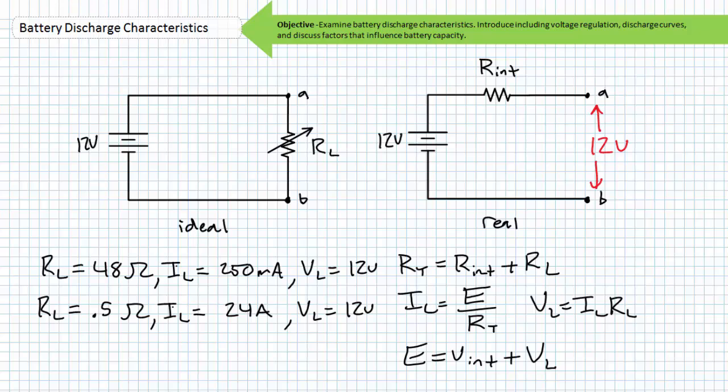of self-discharge over time. When an electrical load is connected to the battery, the internal resistance and the electrical load are placed in series with one another. The 12-volt source sees not just the resistance of the electrical load, but rather the resistance of the internal resistance in series with the electrical load.